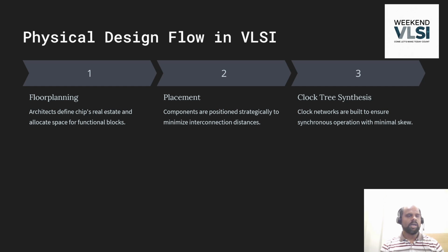Okay, and also, when we are doing your actual route, the NDRs will be specified. Okay, how the clock path should look. It should have double width. The spacing between these two clock paths or the data path which will be coming, or if you want some shields, we will do the shields. All those will be taken care of here.